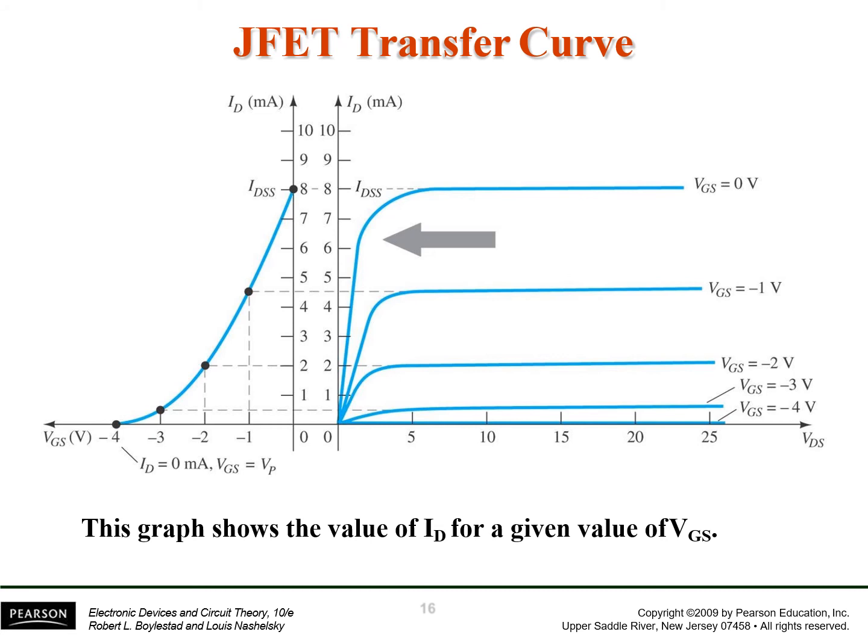Similarly, if we increase this to minus 3 volts, then ID would saturate at 0.5 milliamperes. If we further increase the voltage between the gate and the source to minus 4 volts, the current through the drain does not increase from 0, and it remains at 0, as you can see in the blue line on the x-axis of VDS.